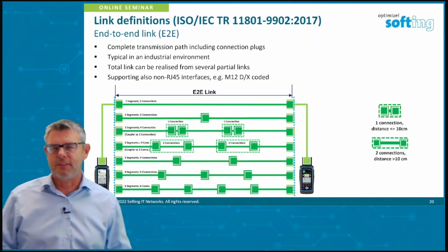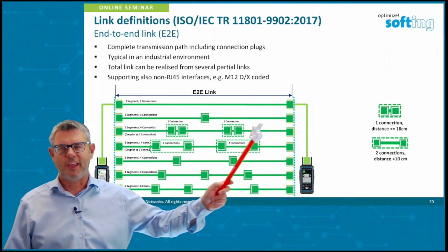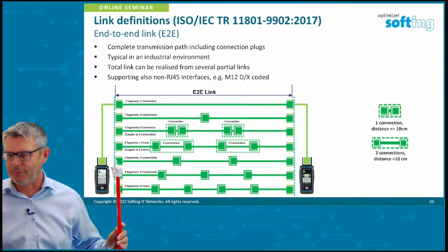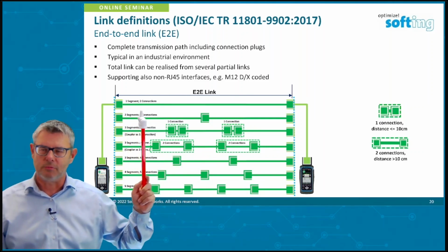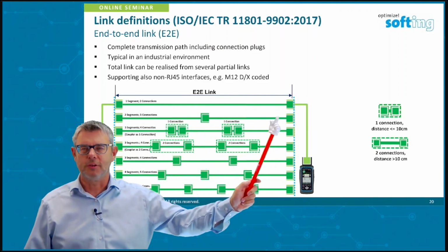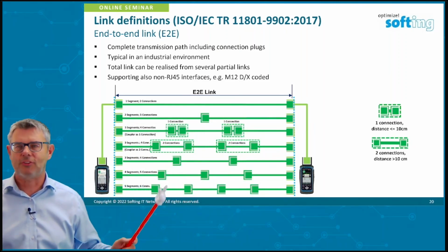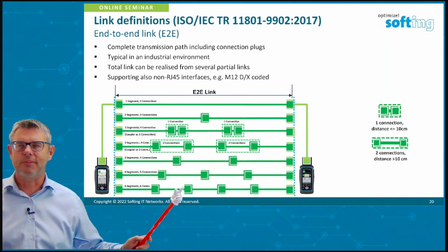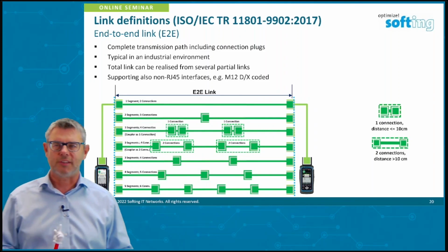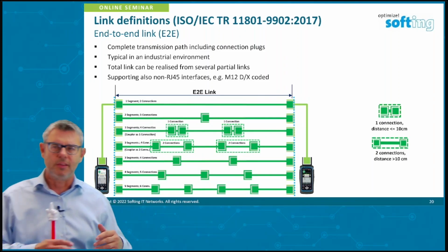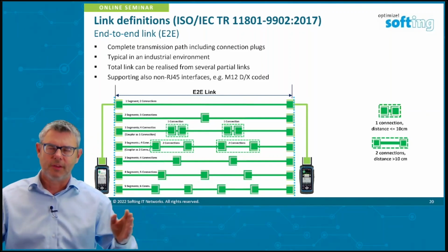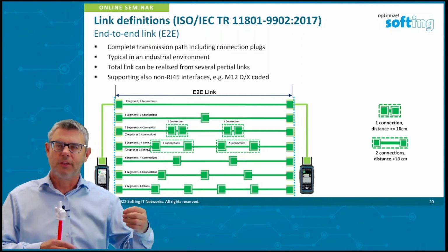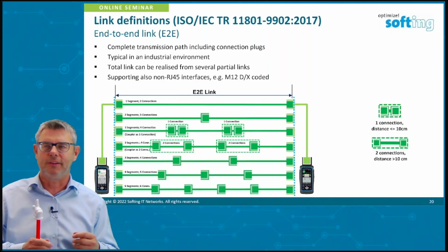What's also different is that this cabling can be built up in certain parts. So it doesn't have to be like in the office building, one cable through. We can allow up to 5 connections in an industrial environment. The reason for this is that in an industrial environment, sometimes you have to connect to a machinery, and the machinery is encapsulated. And to make sure that you are moving properly between the different layers of the encapsulation, you have to open up or break the test cord.